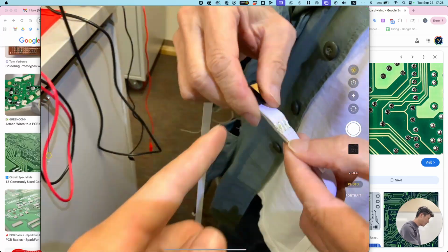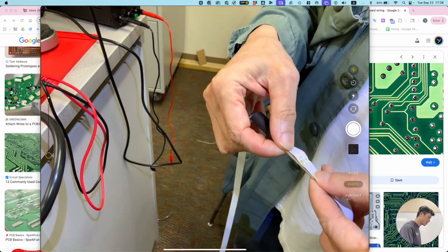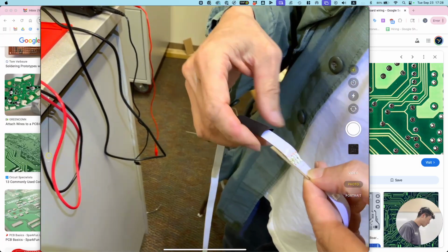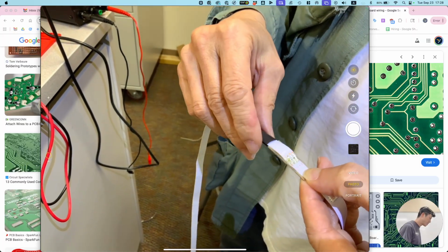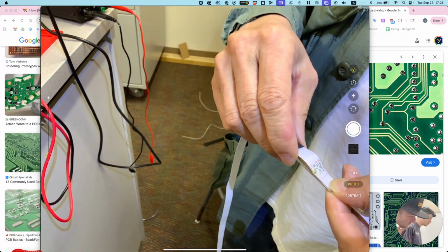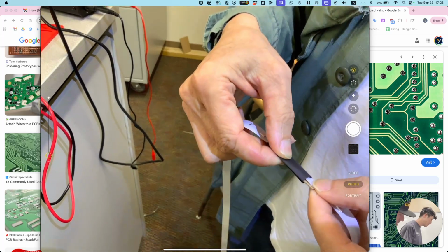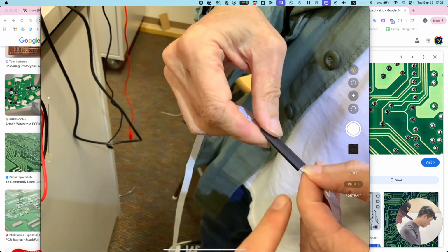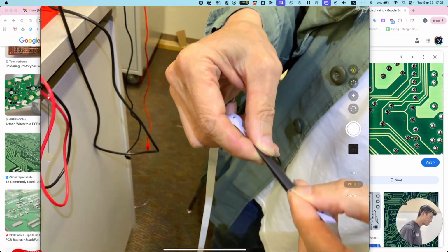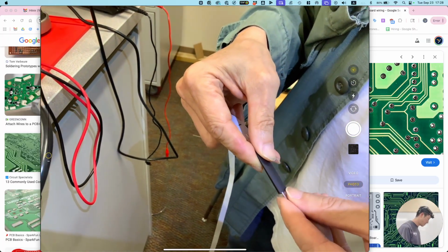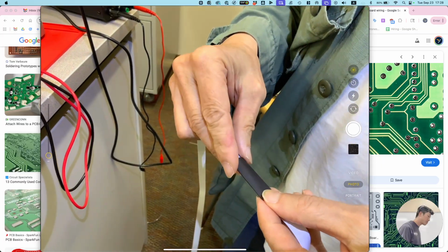So we put a split back there because the solder joint is weak, so we don't want to break it again. And then we're gonna slide a heat shrink on top to seal it all in. And then he's tucking the split so that none of it shows up from underneath. That way we don't crease the line in the future.